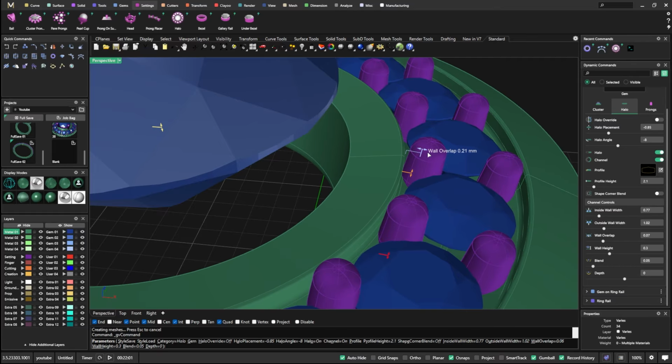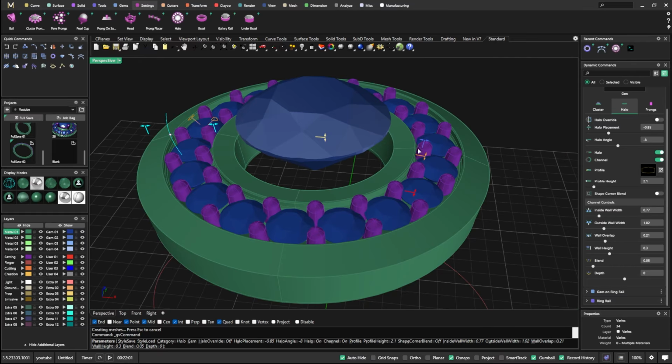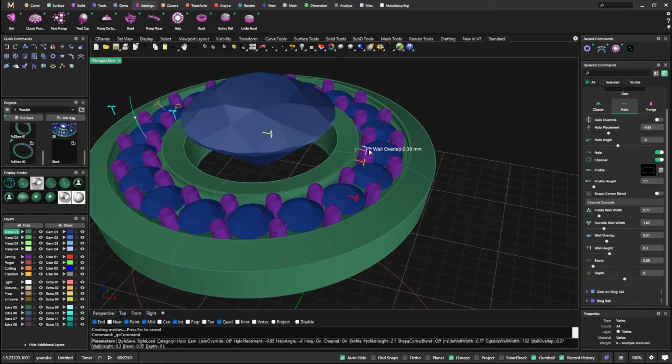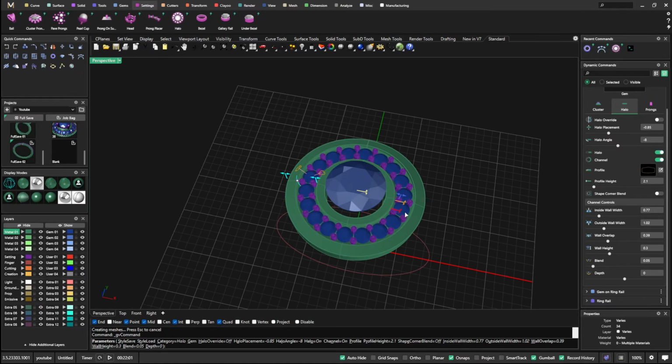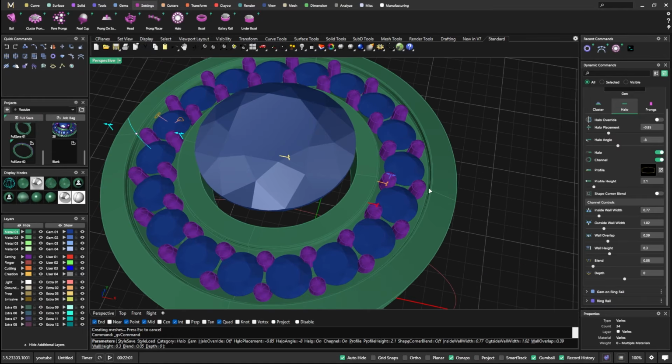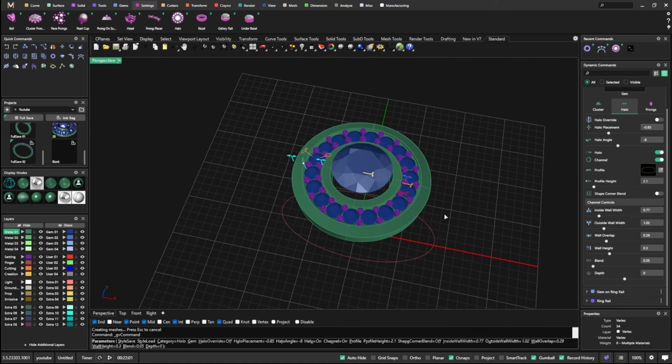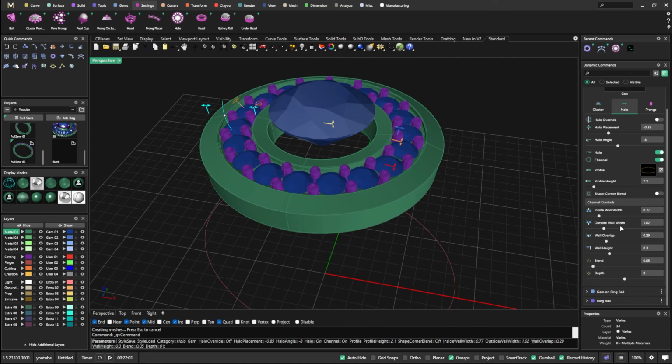You want to open that up a little so that your prongs have a little area there, so they're not going to be tied up during casting, and all that's going to be inside there, right? You probably want them out a little bit so that you have a little space in between each of the prongs. Okay, so that's very important.